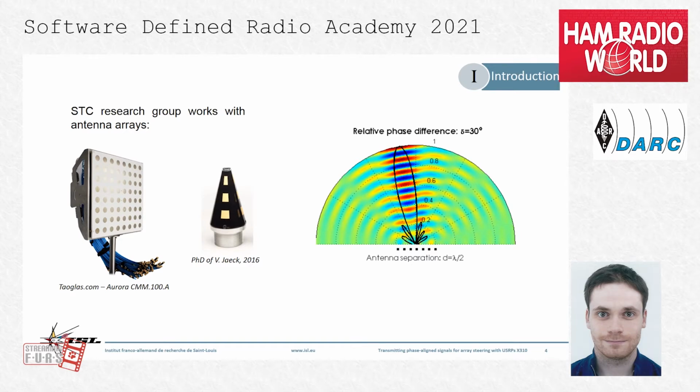And antenna arrays also allow to dynamically change the resulting radiation pattern by modifying the phase shift applied between each antenna signal. Here, by imposing -30 or +30 degree phase shift, the main lobe of the array can be steered towards -10 or +10 degrees, respectively.